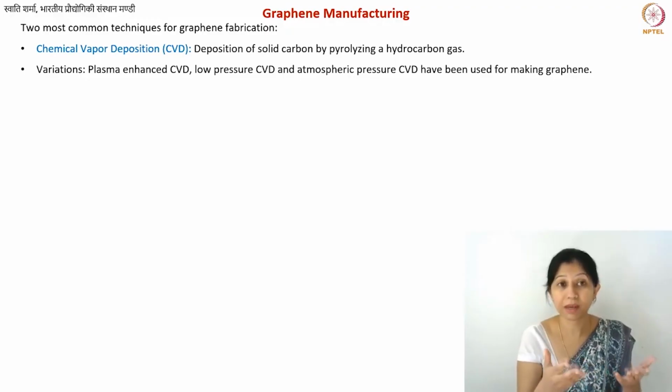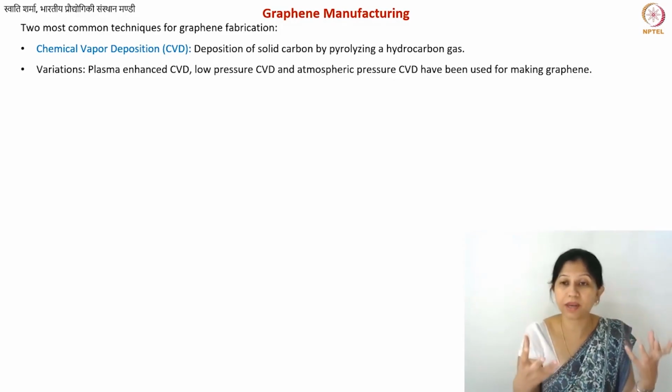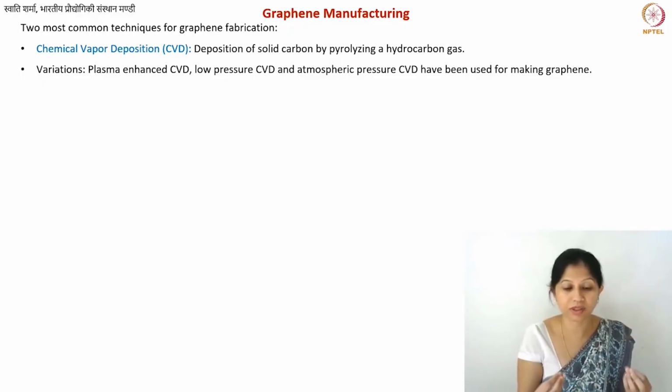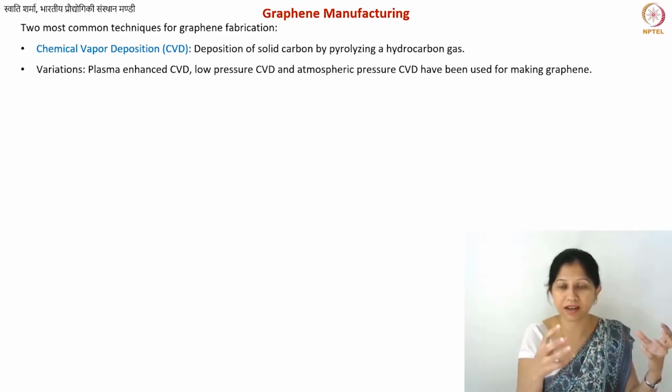As the name itself suggests, you have a plasma, which can be argon plasma or any other type of plasma, which is basically an ionized material, so the ions will transfer some energy, sort of activation energy, to your chemical process. And also the deposition process. Sometimes they will also improve the diffusion of the species that have been formed into your catalyst. So basically you can perform the process at a lower temperature. So that is plasma enhanced CVD.